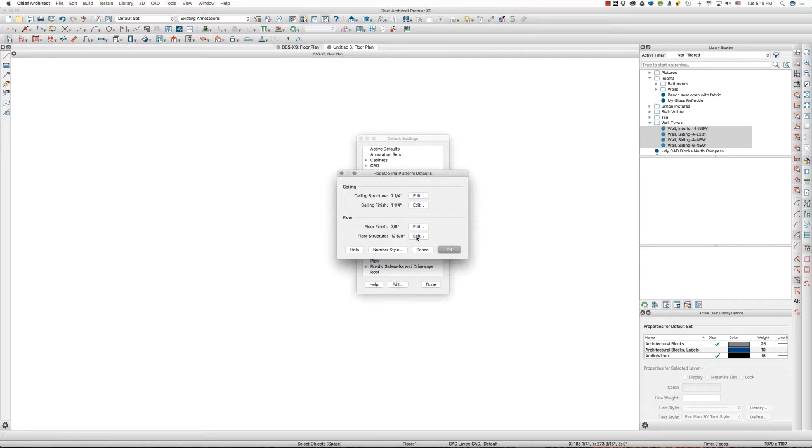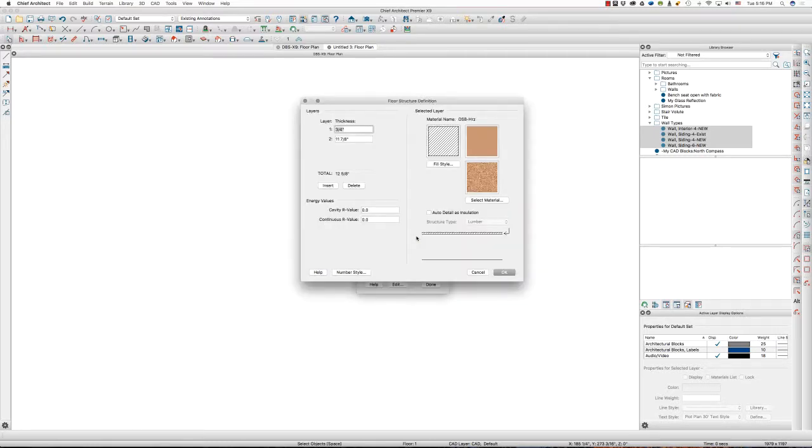In my floor structure, I'm going to go ahead and leave it as 11 7/8 inch I-joists for now. That will change with each project as I go along. But I like to put some angle hatching at 3/4 inch spacing for my subfloor, and that just kind of gives an idea. All those lines there, when we've got sections, we've got the floor joist, we've got the subfloor, we've got underlayment, and then it's just a lot of lines. So I hatch the OSB subfloor that's 3/4 of an inch thick, and it just shows up a little cleaner in my sections.